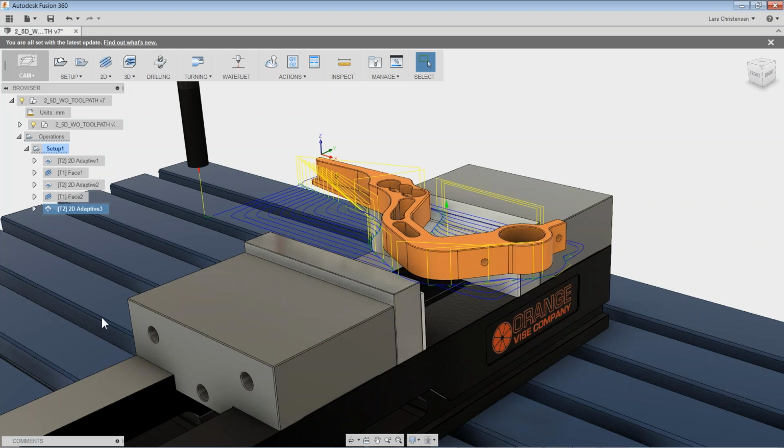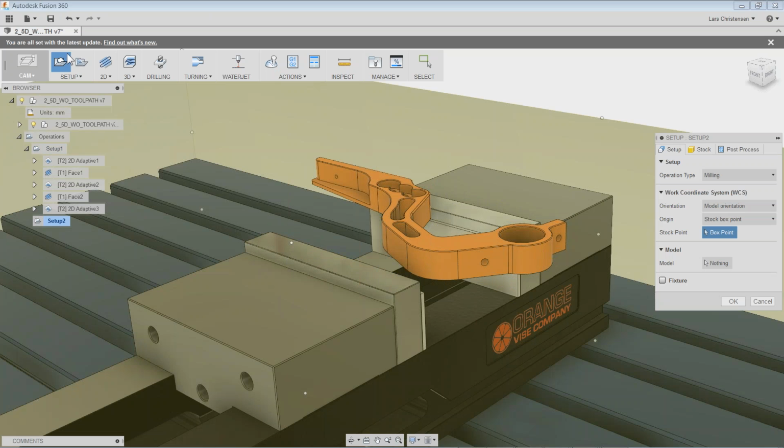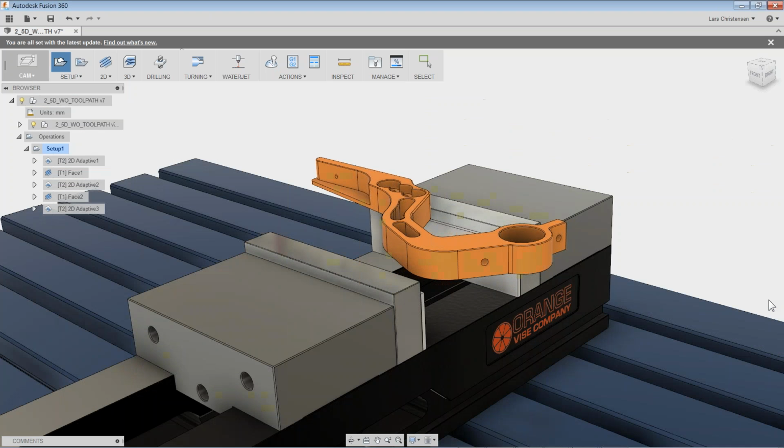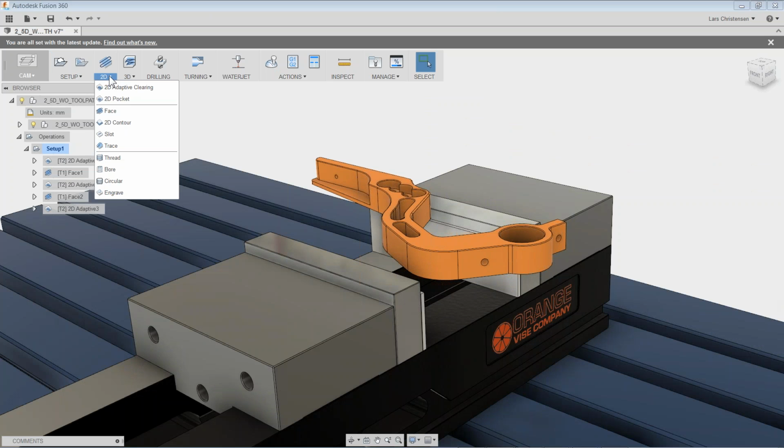So I really hope that in these 40 minutes, and I know there are some good questions I'm looking forward to answering, I've given you an insight into the steps when it comes to creating tool paths inside of really all 3 products. It's really just about going in and setting up that setup, picking what you're going to machine, setting up your work coordinate system, how you want the Z-axis and the X-axis direction, and then applying your tool path.